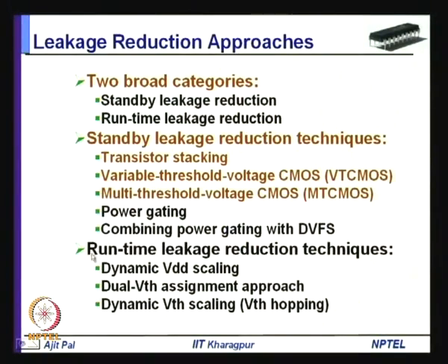For standby leakage power reduction, there are several techniques. Number one is transistor stacking, second one is variable threshold voltage CMOS, VT CMOS, third one is multiple threshold voltage CMOS, MT CMOS, and actually this MT CMOS technique has become more matured, and this is known as power gating or power management.